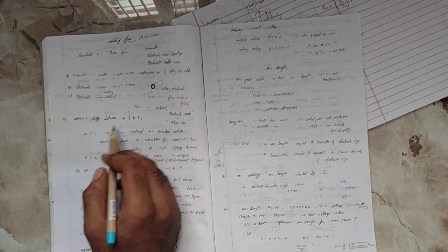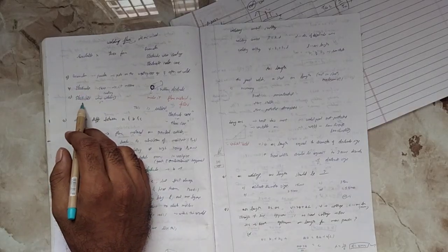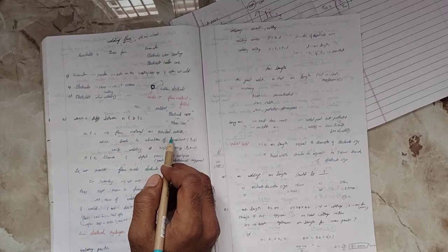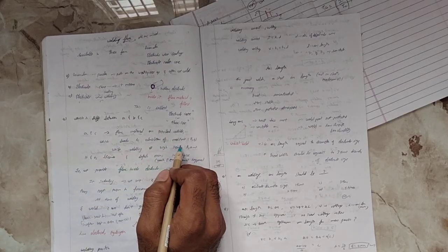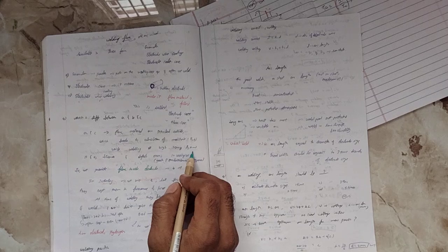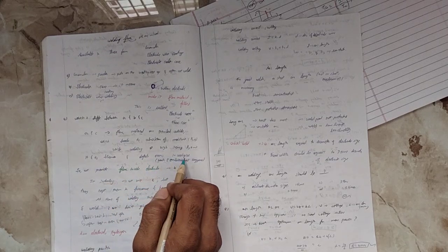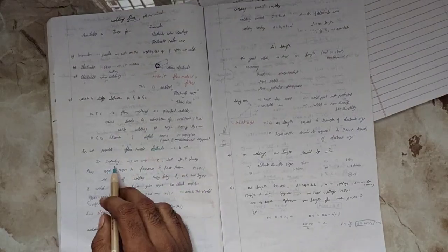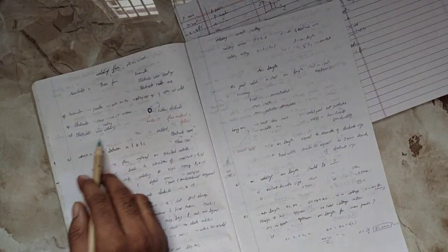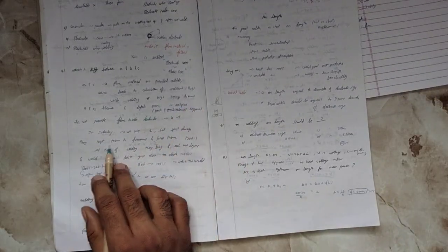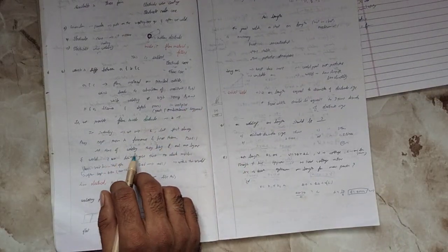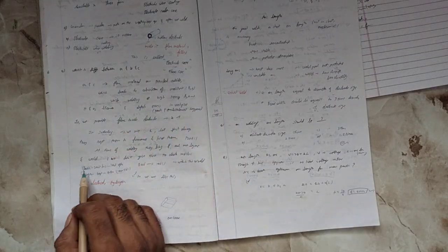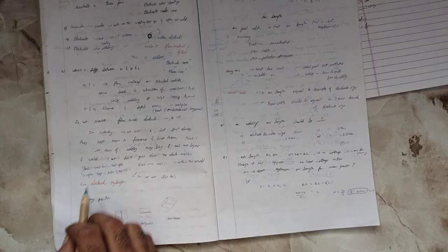So what is the difference between A, B and C? A and C are the granular electrode and the electrode wire coating, so the flux material is provided outside, which definitely leads to absorption of moisture. While welding at higher temperature, H2O breaks down and hydrogen enters, and defects occur in the workpiece. So that's why we provide the flux inside the electrode. In industry we use C, the electrode wire coating welding. But we always keep them in the furnace and heat them, and at the time of welding they bring them out and do the welding. I think you're getting the point. Generally they keep them at a higher temperature.